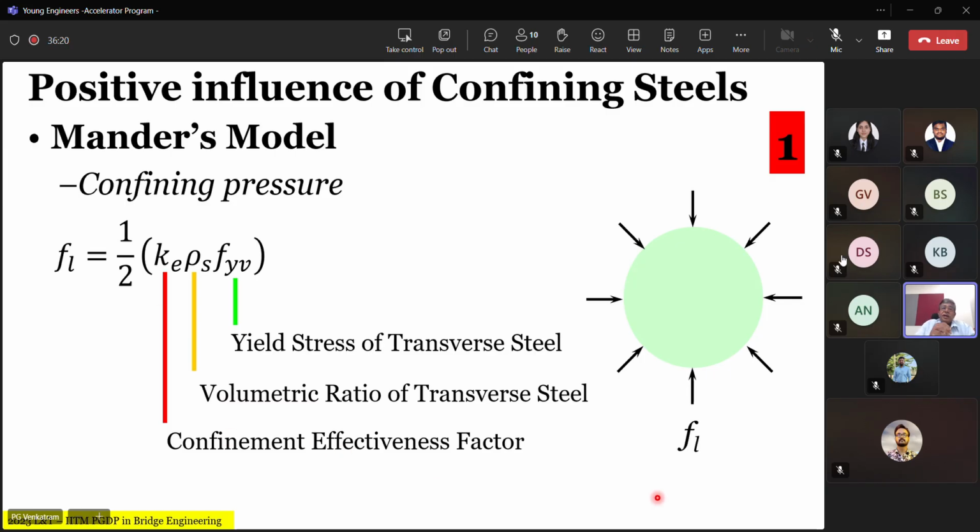Now, this tends to give you a feeling that if I use a higher strength bar for confinement, I will be better off. Actually not true, because with high yield strength bars, you will tend to reduce the area of steel from the strength point of view, and therefore you will end up having less stiff transverse confinement.